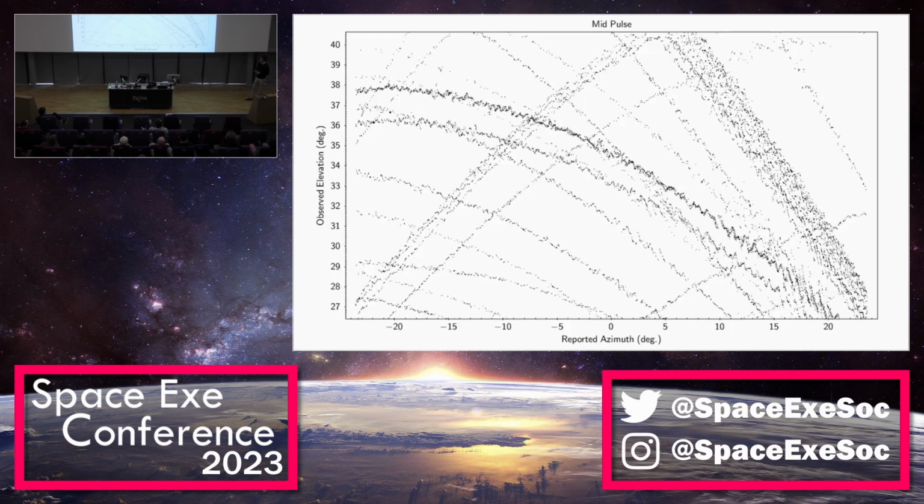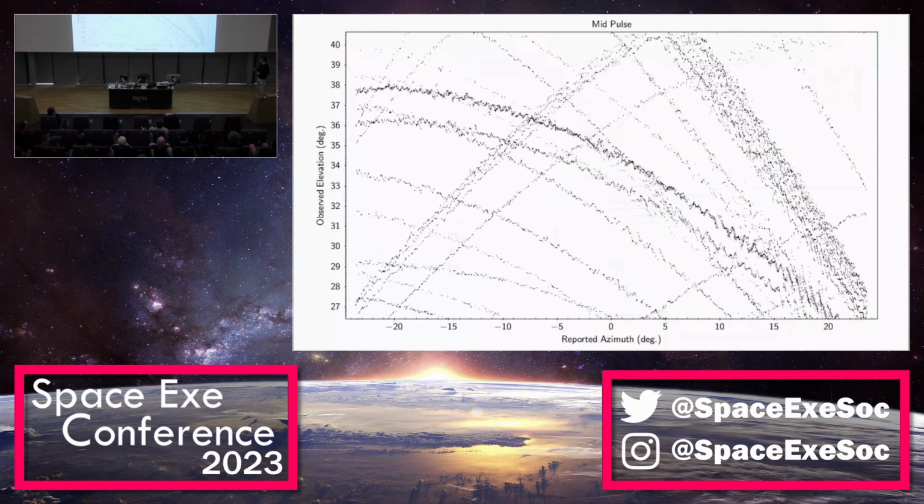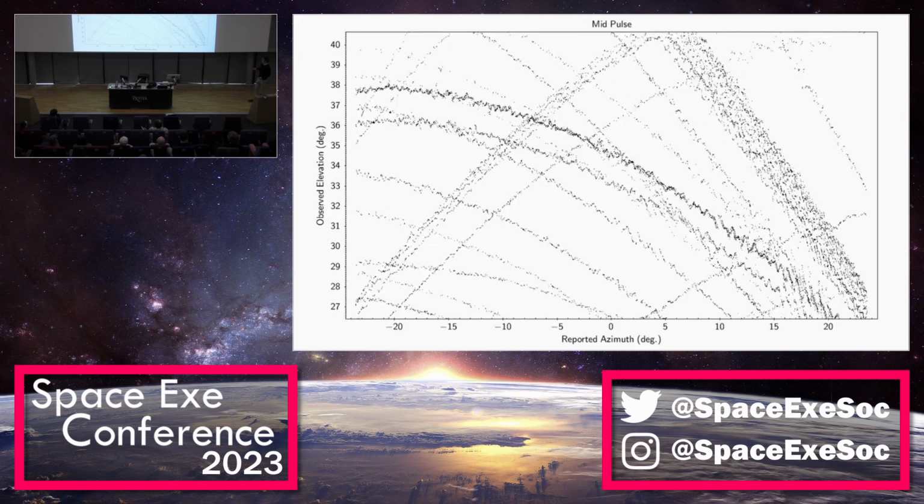My supervisor had the idea that the direct signal is actually the shortest time signal. This is the most direct route light can take, and this is from Fermat's principle and Snell's law. So it's the shortest time route, and these reflected signals will be received at some later time. So why don't we just take the phase measurements from the leading edge of the signal, the very first signal we receive, and then cut it off before we can receive the reflected signals. After we did that, this is what we saw. Those wave-like structures are almost completely eliminated.